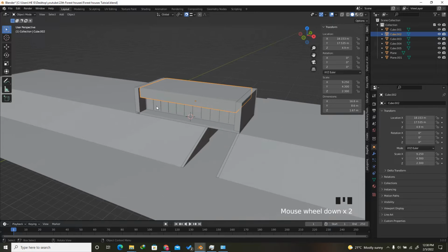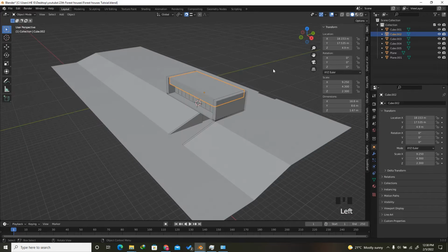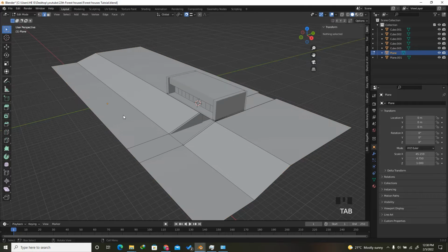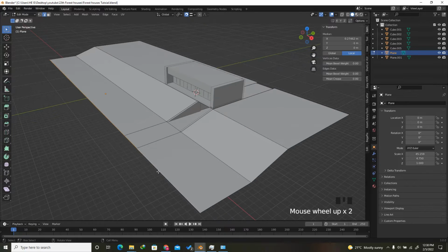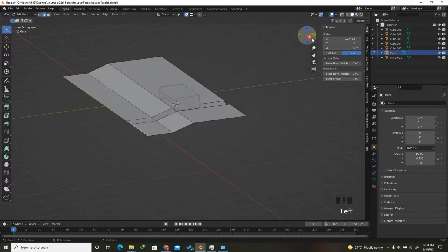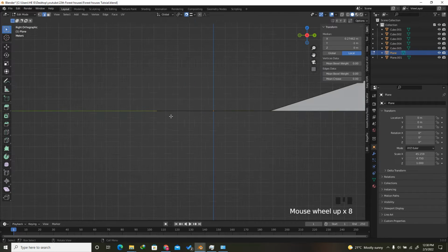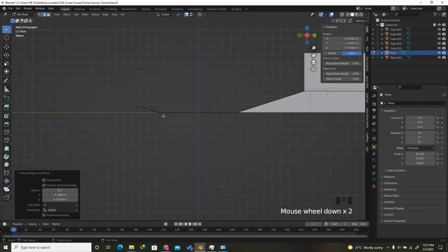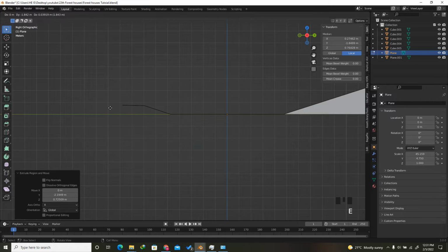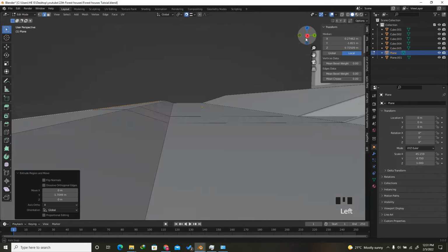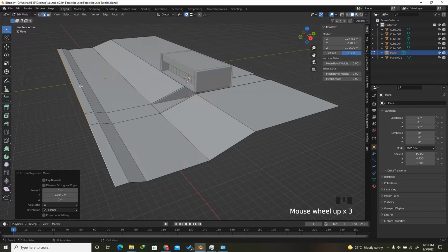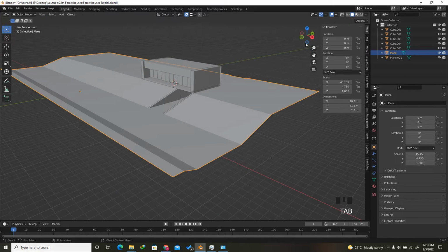So then the one thing that I have forgotten is I'm going to select this ground and press Tab and go inside the edit mode, and I'm going to select this edge by holding Shift, and at first I'm going to get inside right here, and I'm going to press E to extrude it, and I'm going to extrude it maybe something like this. Yep, and then E again, and then Y, so that it will be fixed on the Y axis. Yep, this is the road, and this will be the turn. So I think I finished.